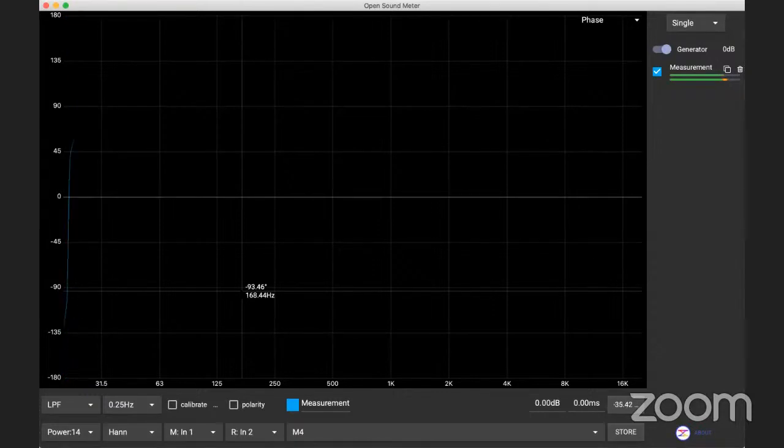We'll be able to see that on the impulse response. The moment I virtually move them behind, not physically, on the phase trace, on the impulse response, you should see them line up, and when you listen to it, you'll also hear a much better low frequency response.